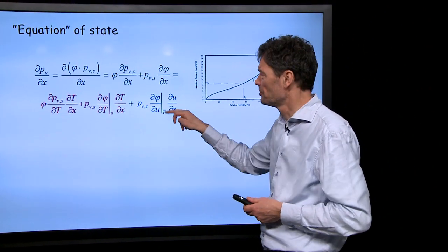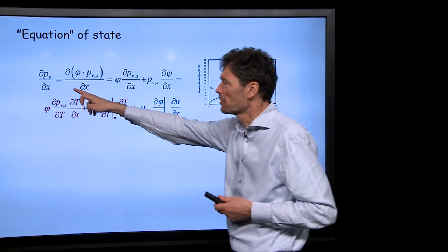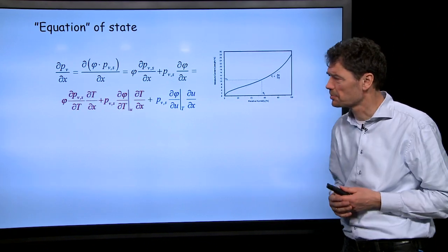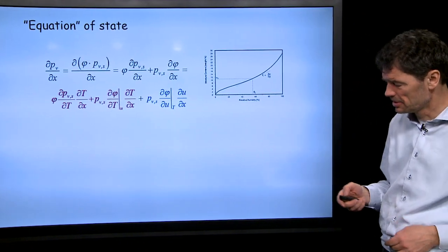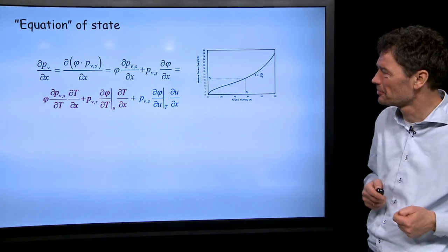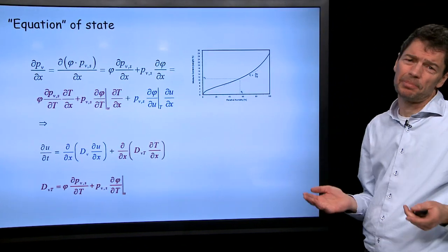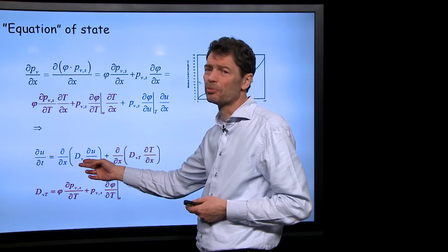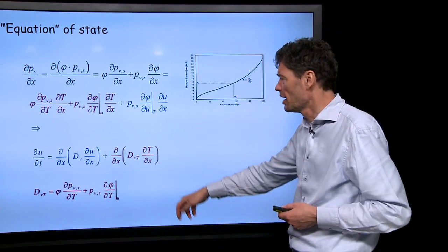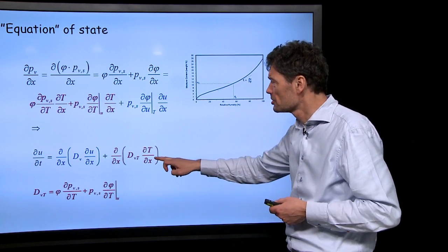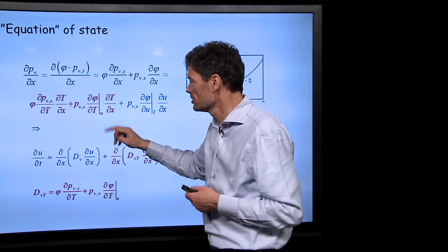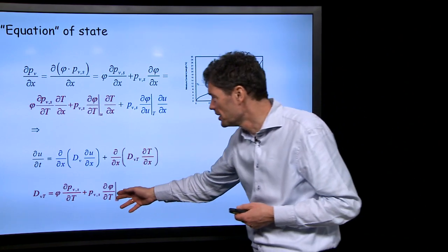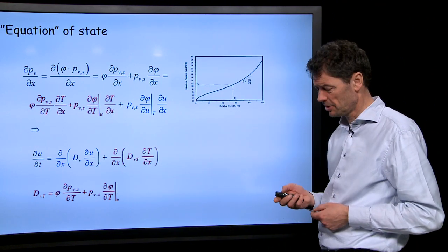Then, what we have from the slide just before, we have the same thing again, how vapor pressure varies with moisture content and how we use the moisture capacity, Xi, to express that. So all that comes together now in this more advanced equation where we consider both the temperature and the moisture effects. We clean it up like before and introduce, again, some diffusivities. So we had in blue, like before, the moisture diffusivity, but also we have a thermal vapor diffusivity. All those coefficients that are driven by the temperature gradient, we can comprise in a variable we call the thermal vapor diffusivity. And here you see the definition of the thermal vapor diffusivity.